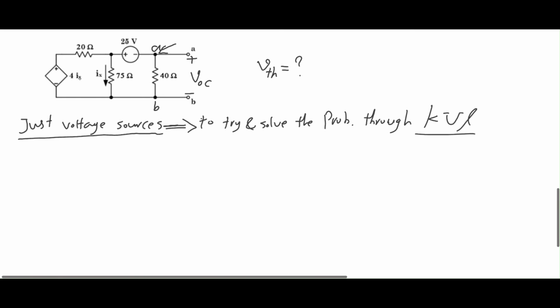What if I had a current source? Yeah, the answer is no, because if I know the current, then I cannot use KVL. But in this circuit, I have nothing but voltage sources. I know this one is a dependent source, which we're going to figure out how to address in our solution. So I consider two currents. Let's call this I1, and this current in the middle loop as I2. And what about this current? Yeah, there is no current. It's zero, because it's open circuit.